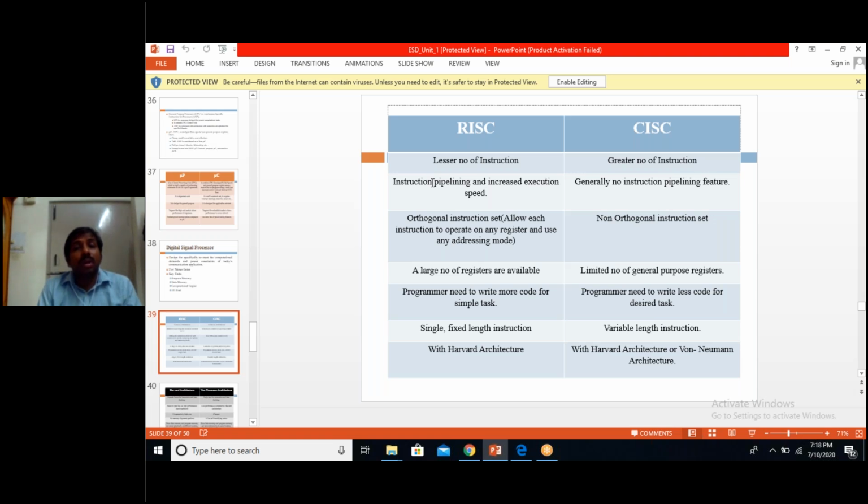Whereas if you go for the pipelining method, the first instruction is processed, and at that time we will be fetching the second instruction. When the first instruction is in the execution state, we will be fetching the third instruction, the second instruction will be in the execution part, and the third instruction will be in the storing part. So pipelining means we parallelly allocate certain space and time of the processor to do multiple instructions at a time. One will be in the fetching state, one will be in the execution state.